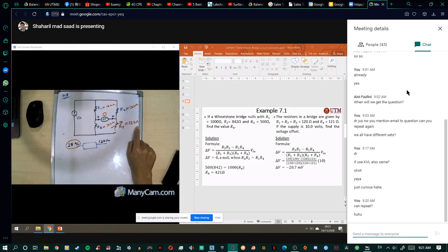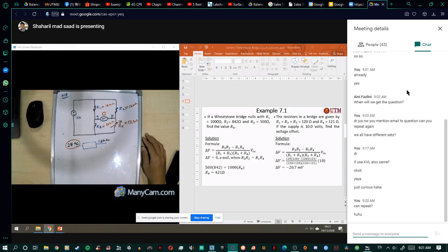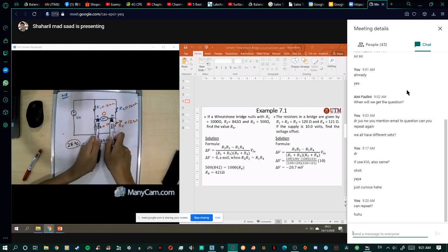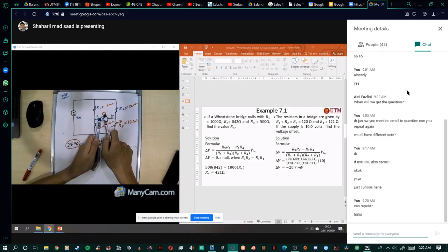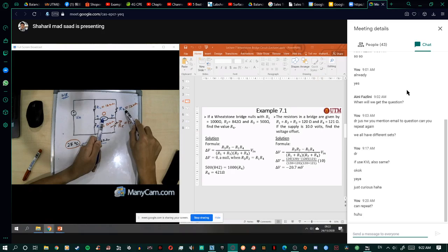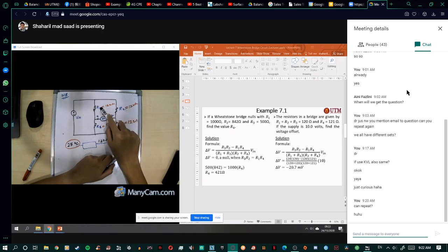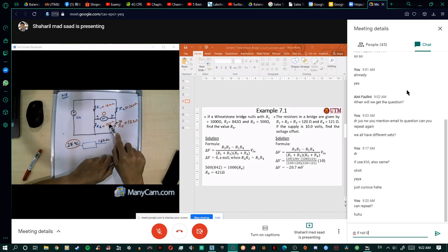Okay, so of course when you want to start your measurement, your multimeter, when you put your multimeter at point A, should be 0, right? So that you can start your experiment in order to measure what happened in the room temperature after that. So in order to make the multimeter read 0, you need to choose the resistance value 120 ohm for R2, 120 ohm for R1 also, and R3 120 ohm, right? And this resistor transducer is 120 ohm.